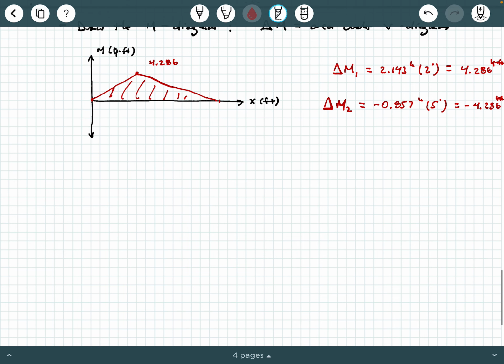Let's make a couple of last notes on this, okay? I'm going to change colors here. Notes, all right? So when you have a point force on your beam, that is going to give you a constant shear force, which is going to give you a linear moment diagram, okay? Now, let's think about this again. Remember, because you're integrating, right? You're integrating from load to get to shear, and then you're finding the area beneath the curve to go from shear to moment, all right?